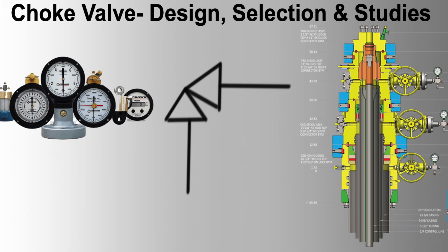Disadvantages: inflexibility, flow rates cannot be adjusted once installed, limiting operational flexibility. Not suitable for variable flow, ineffective for applications requiring frequent flow adjustments. 6. Positive choke valves. Example, used in well testing operations where discrete flow rates are required.